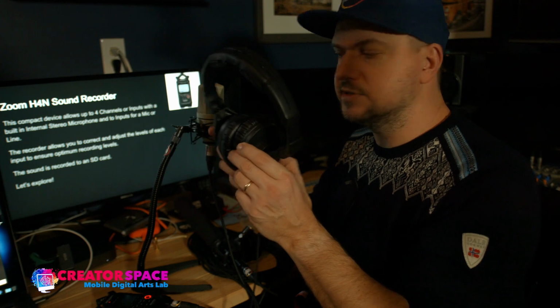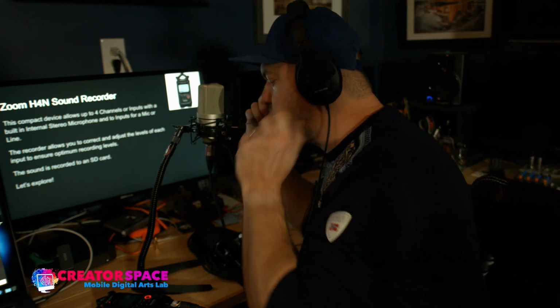The great thing is you will actually hear on the condenser on the left, channel 1, and you'll hear the shotgun mic on 2. So you'll hear the two levels between the two people. So I hear the condenser mic in this ear, check, check, and then I hear this one in the other ear. So I can easily monitor if one is getting too hot, or if there's any kind of clipping, or keeping the levels in a decent range, right?